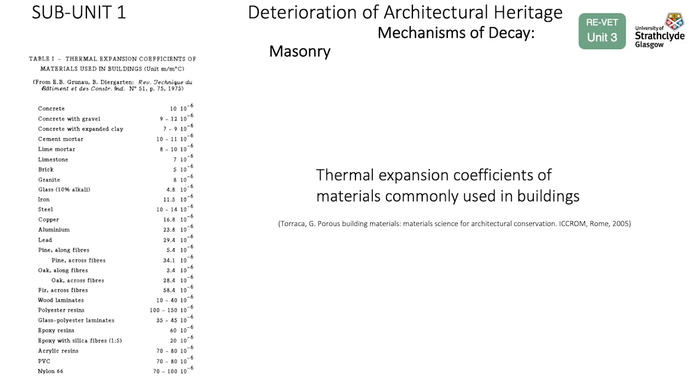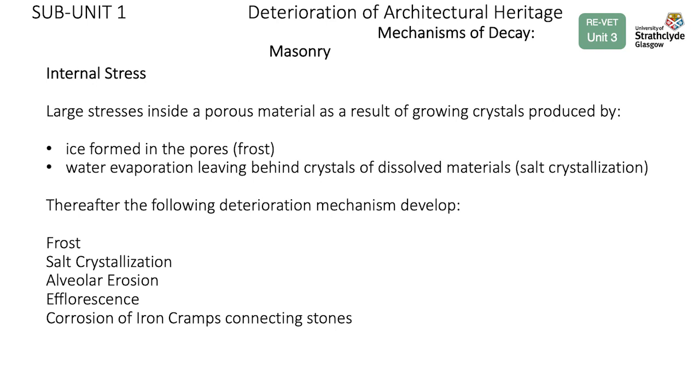Large stresses can happen inside a porous material when crystals of ice are formed in the pores, frost, or when water evaporates, leaving behind crystals of dissolved materials, salt crystallization. The following deterioration mechanisms develop: frost, salt crystallization, alveolar erosion, efflorescences, corrosion of iron clamps connecting stones.